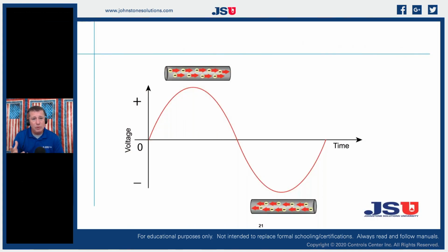Because what we do with 5 volts DC is we take an AC voltage, we're taking that 24 volts AC that we started with, and then we're going to add in some diodes so that we can chop off part of the peaks of the sine wave so that we're reducing the voltage. And in the process of doing that, we're creating plateaus that we can send signals on, flat spots that we can talk on in that now DC signal.